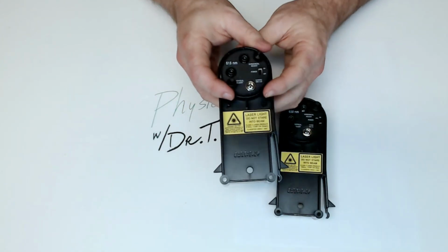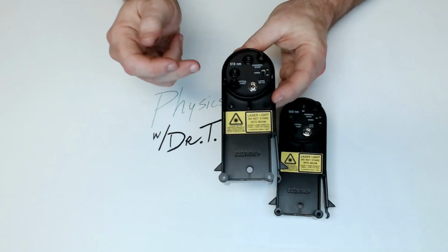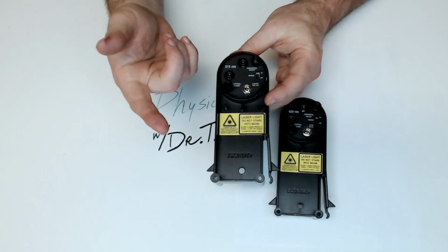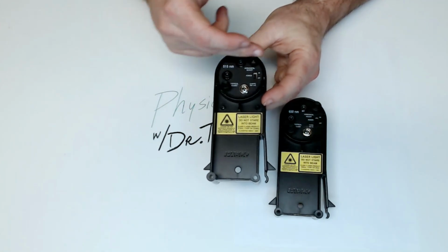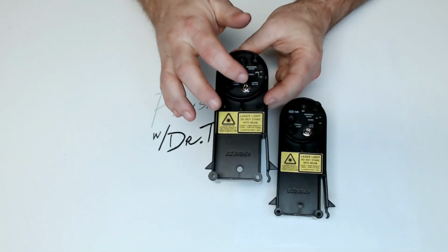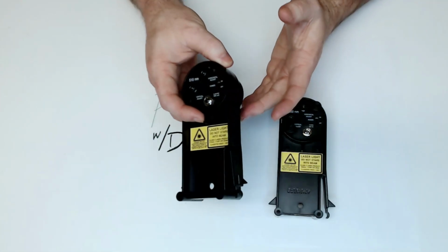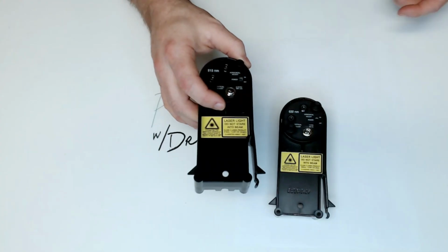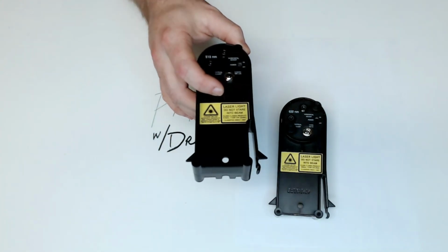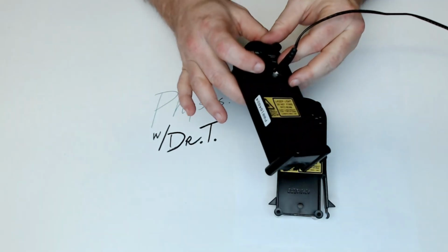You also have a couple of controls. This will control the movement of the laser beam, or the alignment, if you will, on the track. This is vertical adjust, so it'll move it up and down. This is horizontal adjust, so it'll move it left and right. And then you've got your power source and the power control. Please remember, to get the longest lifetime out of these, we want to have the power off anytime you are disconnecting or reconnecting power. And so you plug that in, and then you press power,